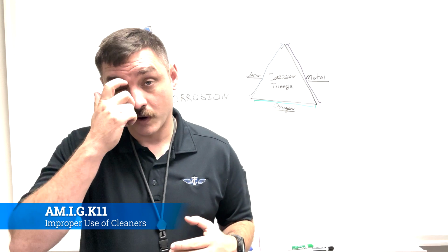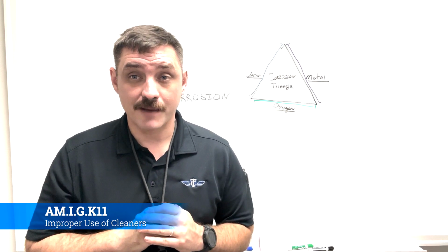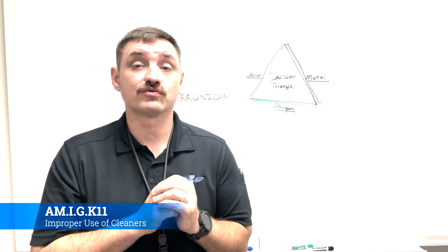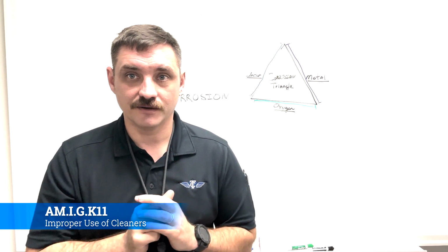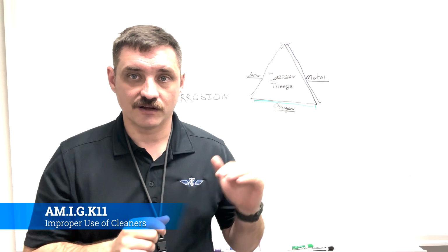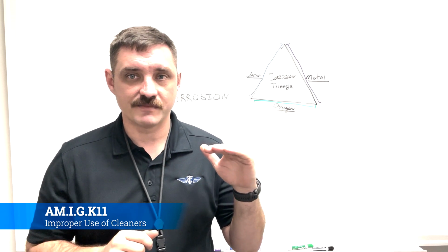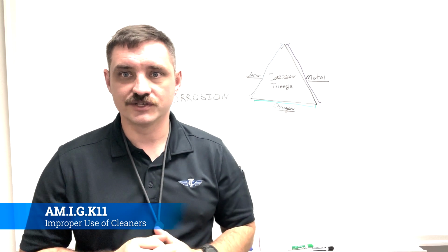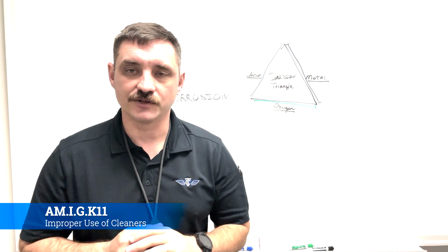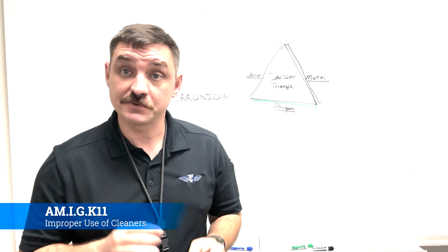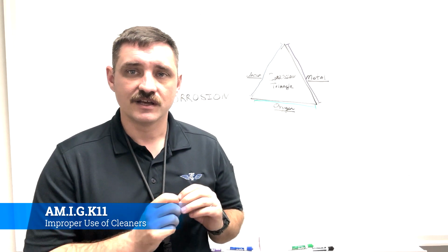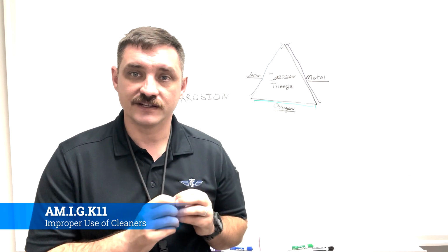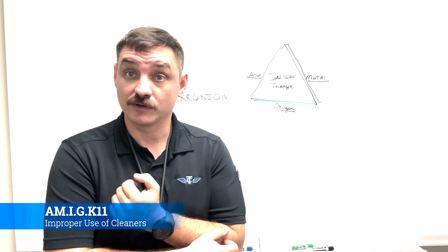And as we saw with Hawaiian Air, corrosion happens with an extremely vertical inflection point. It's not really that bad, it's not really that bad, and then all of a sudden it's way bad, in no time at all. That's really dangerous, especially with composites, because you have such a narrow window to find something so small that could be really drastic.